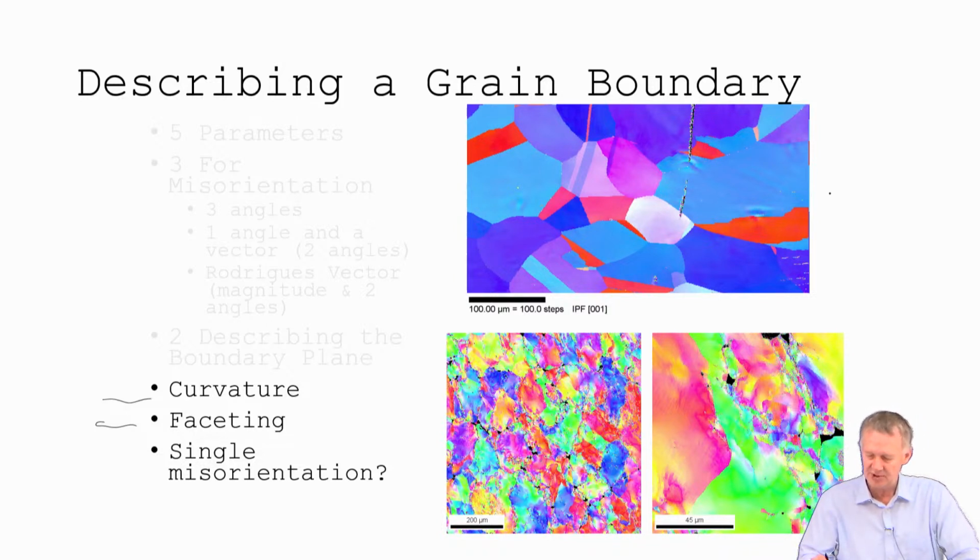Here are just examples of different types of structures that would be particularly problematic for doing grain boundary statistics, right? If you have a highly deformed material like this one, it's really hard to even define a grain boundary using EBSD. Because you say 15-degree boundaries and they're going to be discontinuous boundaries everywhere. It's not even going to create a nice cell structure.